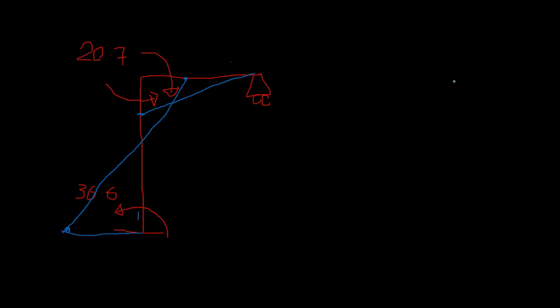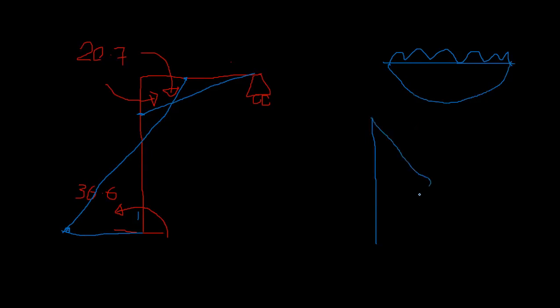But you have some simply supported loading, right? So you have something like this and something like this, simply supported, right? I told you this load is not going to affect, it's acting directly on the joint and it is acting axially to this member. So neither member would have a bending effect due to this force, right?